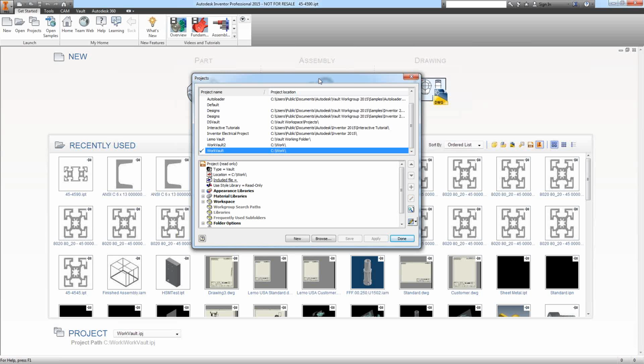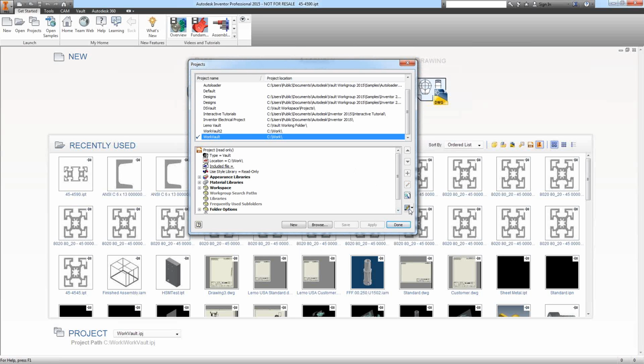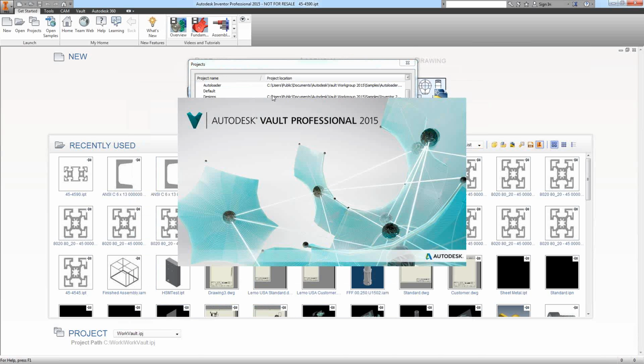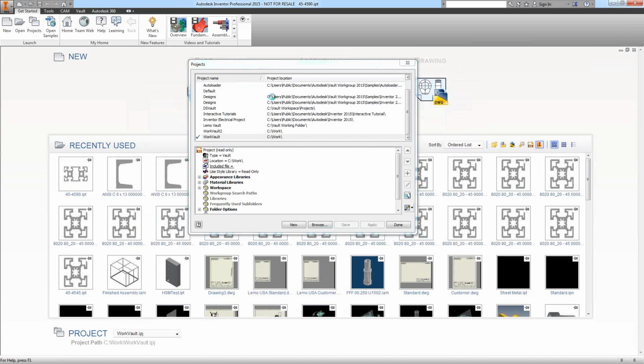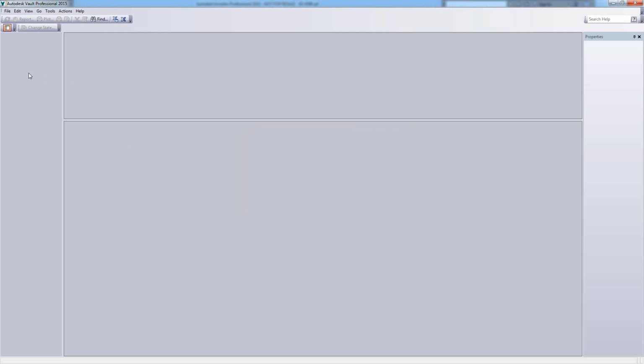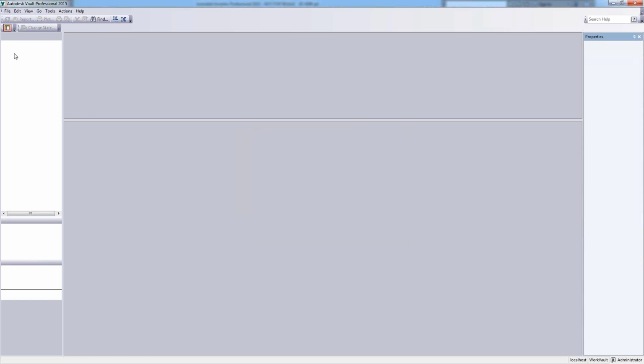because you may not have a connection to your Vault while you're traveling, or if you're connected via VPN in a hotel room, like I often am, the connection can be really slow, and it can get a bit frustrating to use Inventor. Right. So whichever route you go, you've specified the libraries that are available to you via your project file. Now, your project file has to be read-write, I'm sorry. Mine currently is not checked out to me. So if you're in a Vault environment and you need to modify this kind of thing, you will need permission to check out your Vault project file.